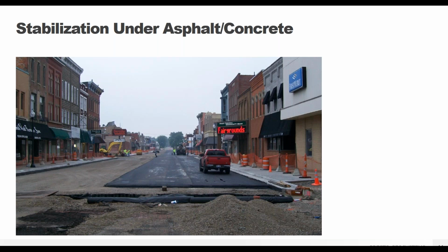So this is just another picture showing that you don't need to have everything in place before you start working. You can lay the GeoWeb system down, fill it in with your stone, and immediately start paving on it. And so you don't need to have any special cure time or wait time with the base before you start paving. You can just immediately get going. And it's your standard paving equipment, nothing special about it. So you don't need any specialized equipment or contractors. You just use your standard equipment and get right to it.